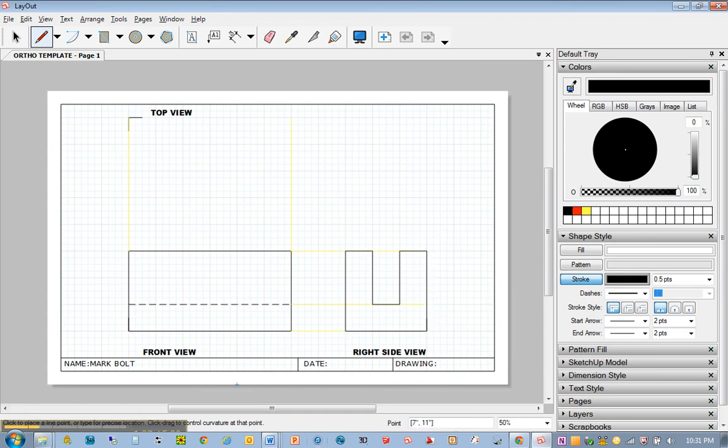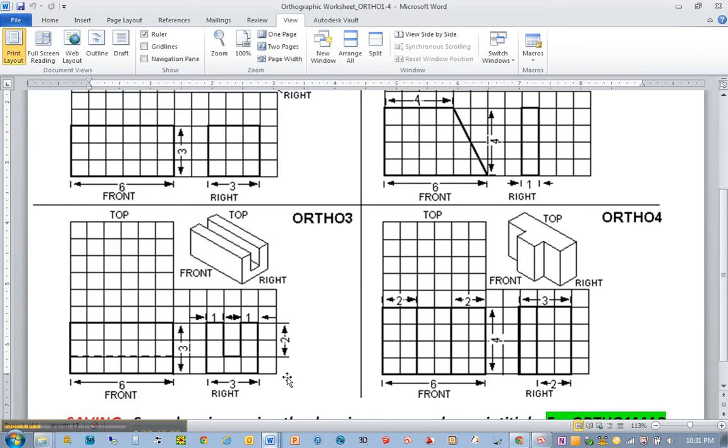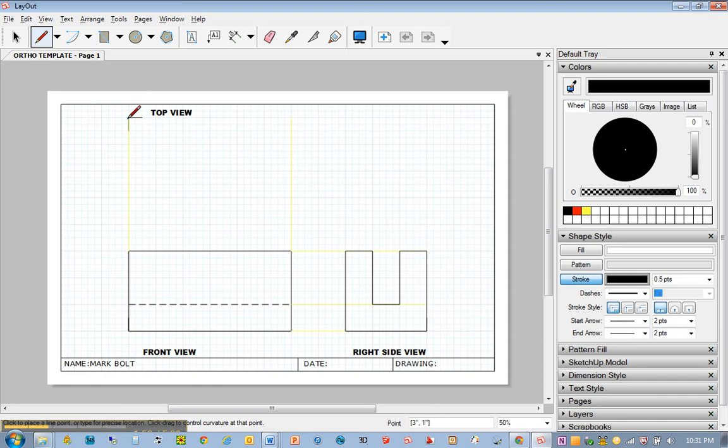There it is. Now, looking at this, I should be able to figure out the length, and the width in the top view is the same number you see here in your right side view. So this is referring to width, which is also in this direction in your top view. This direction is length. So, that being said, I can go back here. I know that my projection line is telling me to start here and to end here. And I'm going to go down a distance of 3, so I'm going to type in 3. Once again, this direction is width in your top view.